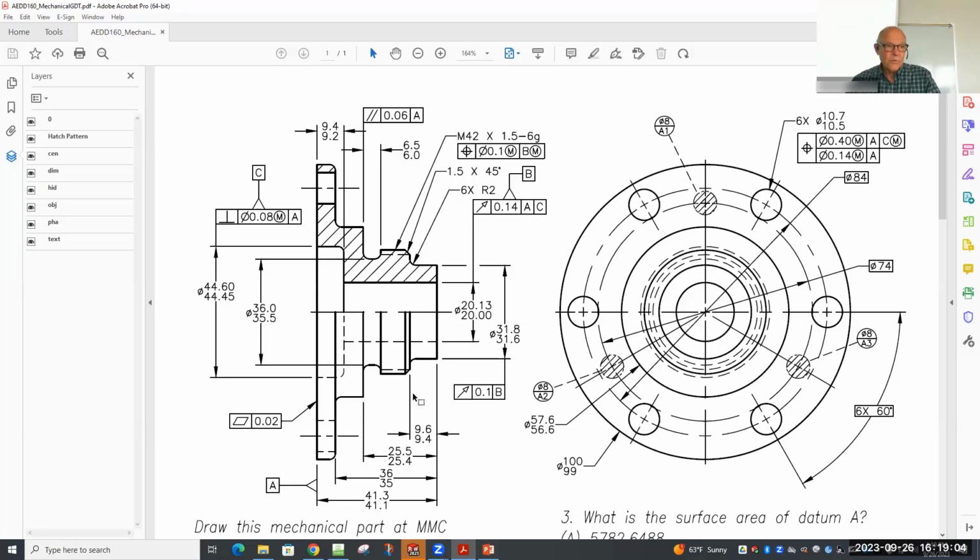So there's something called a tool room, and a tool room machinist is somebody who works in tolerances that are usually 1/10 of the tolerances required for the part itself. So if I'm making a part, a piston that's going to go into an engine, and I say the tolerances on that piston are plus or minus 10 thousandths of an inch, which is pretty big, that means I better build tooling that's plus or minus 1/10 of that amount, which is a thousandth of an inch. More likely, the piston's going to have plus or minus a thousandth of an inch, and that means I better be able to work in plus or minus tenths of a thousandth of an inch. So that's because the tooling you make has to be more accurate than the parts being made.